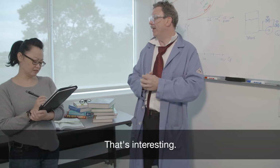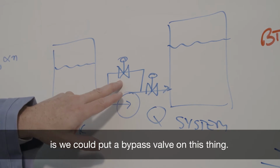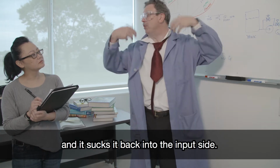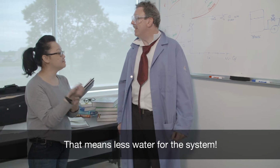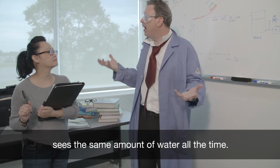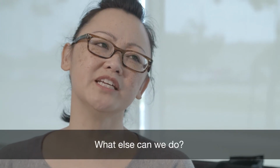That's interesting. Yep. Now, what we could also do, though, is we could put a bypass valve on this thing. And how does that work? Well, what it does is it takes some of the discharge water and it sucks it back into the input side. That means less water for the system. Yes, it does. But the problem is that the pump sees the same amount of water all the time. Well, that's not very efficient, is it? No, it isn't. What else can we do?